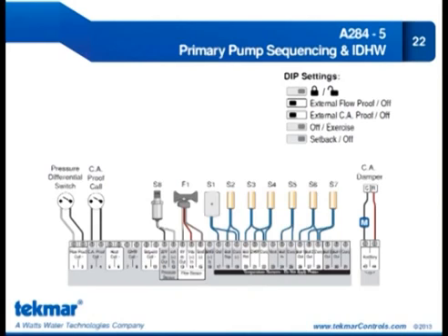It'll be vent. What you would do though in that case, just because there's operation tied, and that's probably where you best tie it into. If you tied into vent, there's a setting called vent max, where there actually was logic imposed to it. But if you turn it to off, then all it does is display. So you could say, hey, hook up your indoor sensor to the vent, and that's mounted in your mechanical room. And it'll display it, and there you go.